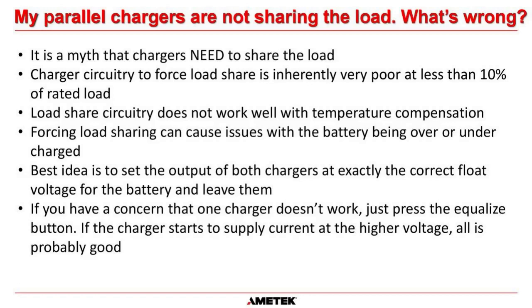Okay. It's one of my pet peeves, forced load share. There's absolutely no reason for it whatsoever. A lot of people will say, okay, well, if I don't see current on charger 2, then I think that it is broken. Well, like I say, just press the equalize button and then see if it takes over the charge. And if it does, the charger is absolutely fine.